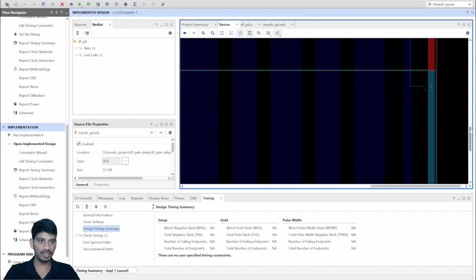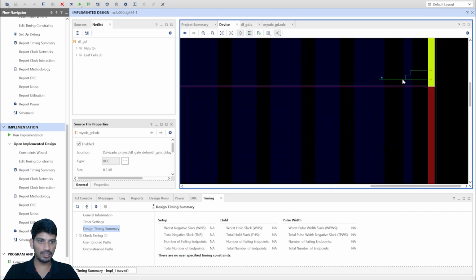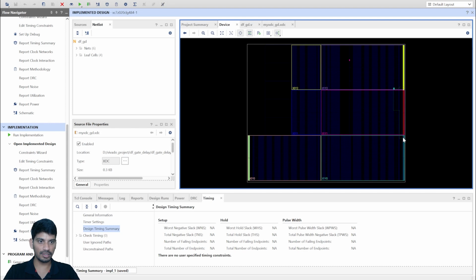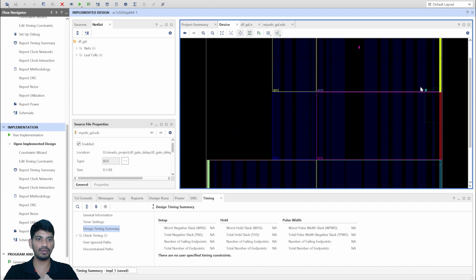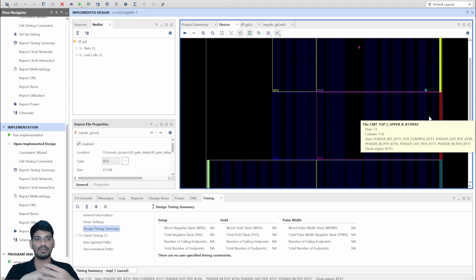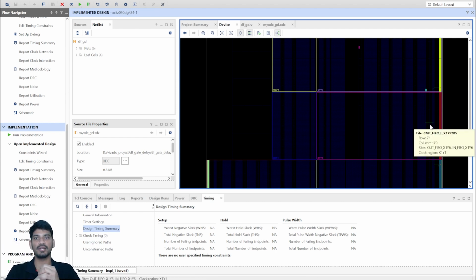Okay, see, the signal is transferring from this location to this location, which is a very huge amount of wire. You can see the wire is very small here, but the wire is in nanometers, so if you elongate it, it will be in kilometers as well. So this will create a lot of delay. That's why delay is a very important thing whenever you design any circuit, right? The functionality will be the same, but because of delay your circuit might fail. See, there is a huge amount of delay associated with just this simple AND gate.